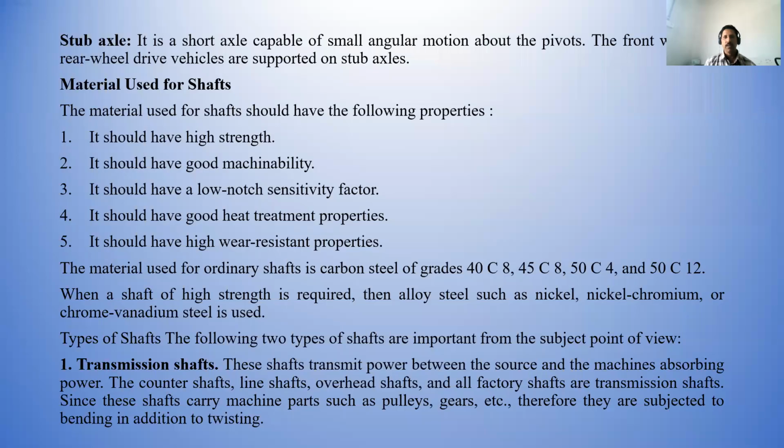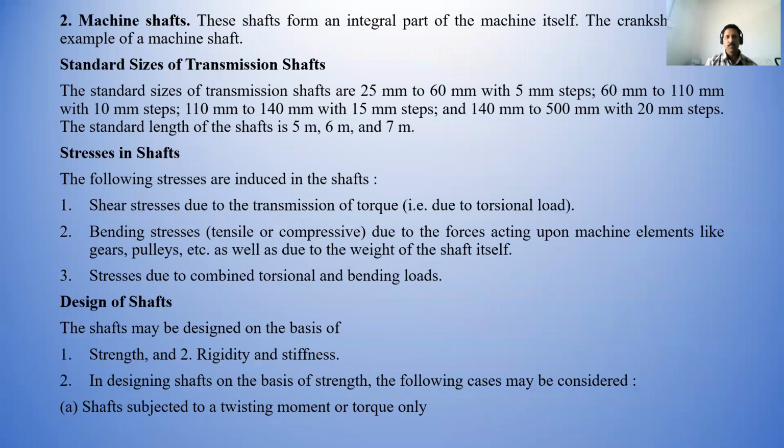In the shafts we have to consider the shear stress due to the transmission of the torque, and bending stresses due to the forces acting upon the machine elements like the gears and pulleys.